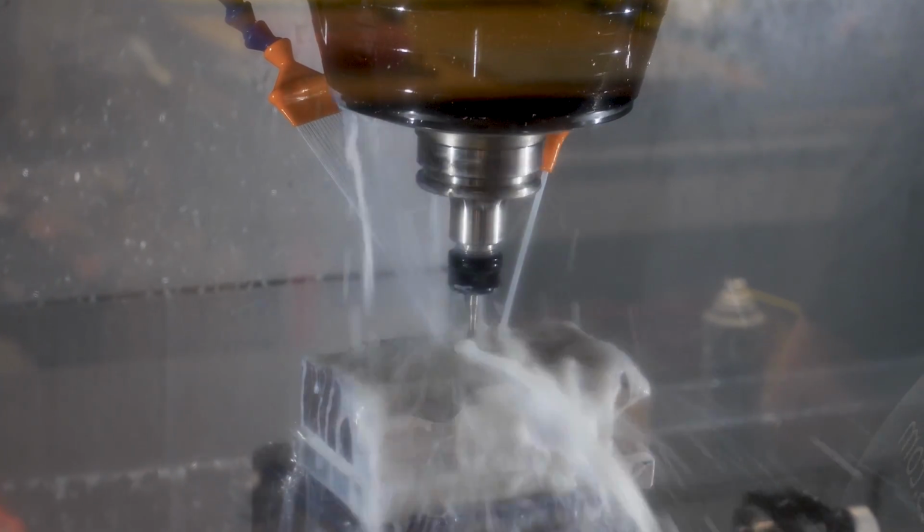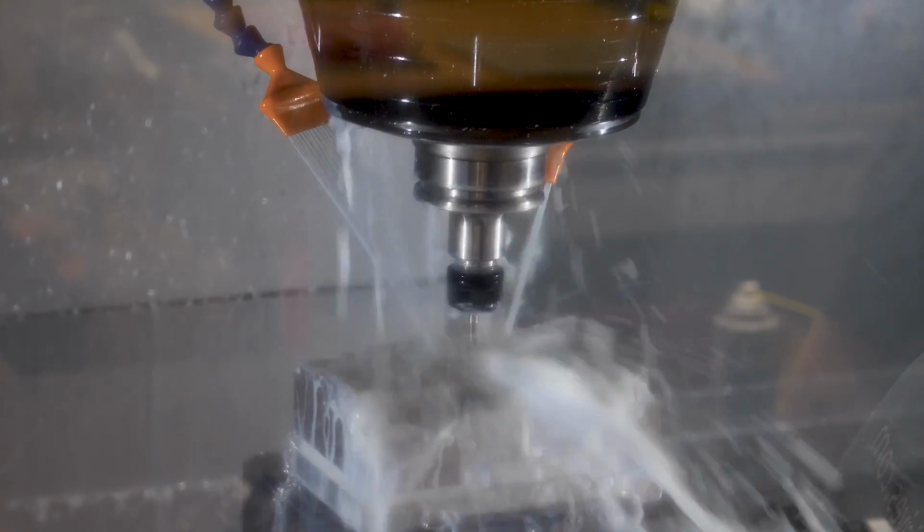A tapped hole is a hole with an internal thread. Threaded holes are very common in machining as they are used to fasten components within a larger assembly. By tapping a part directly, you forego the need for additional hardware. Tapped or threaded holes are created using a thread mill or a tap.